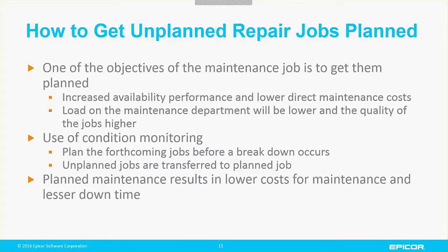information from suppliers of equipment on their recommended maintenance protocols, build those protocols into the equipment, then monitor the performance of those equipments and the frequency of breakdown and, if you like, the mean time between failures. So we use reporting environments against production and production efficiencies, uptime of machines, to then validate that the machine manufacturers themselves are providing us with what is an optimum set of recommended service intervals.